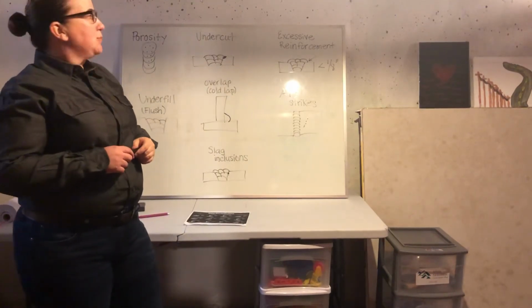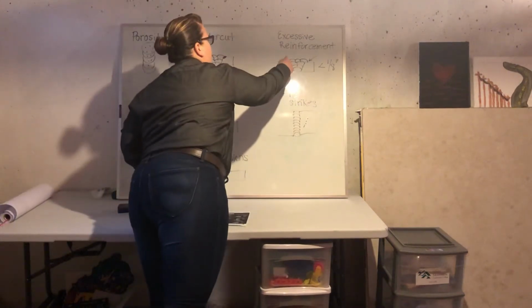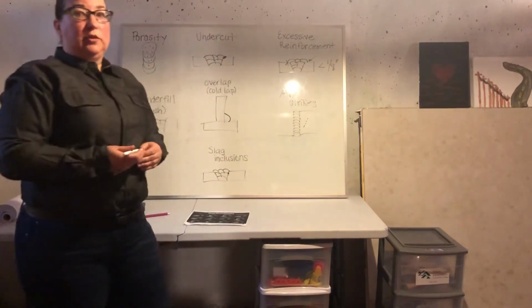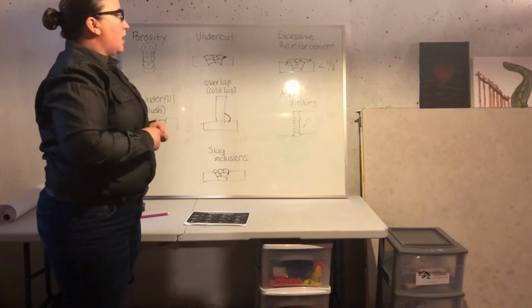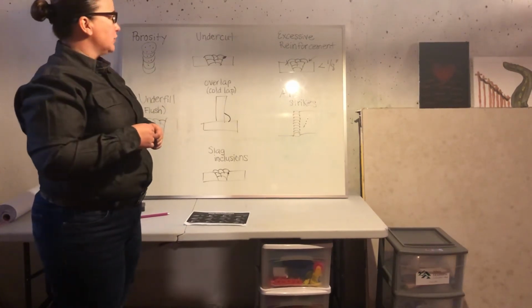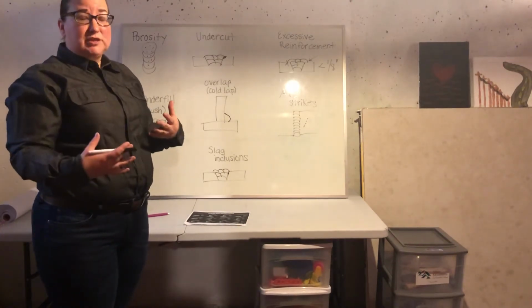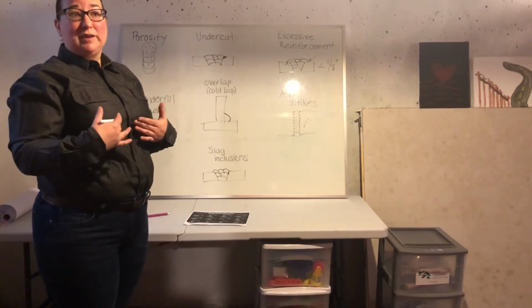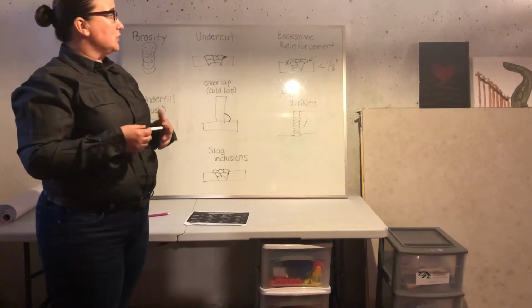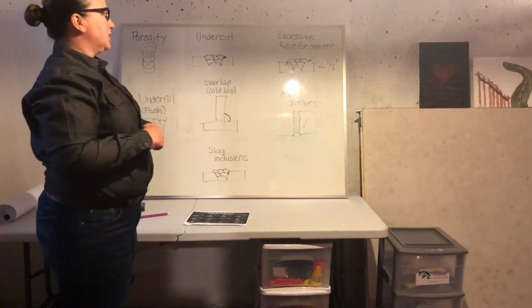So that's a stress point that can actually end up breaking and causing cracking right here in the edge of that weld metal. Most companies are between flush and 1/8 of an inch for your reinforcement. Some companies don't necessarily care, or some procedures don't call for any maximum reinforcement because they'll actually machine that down afterwards, so it doesn't have the same effect.